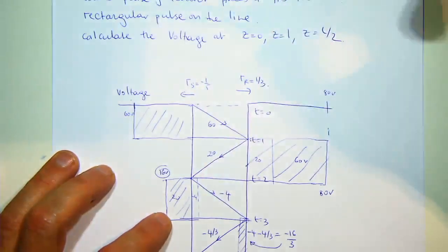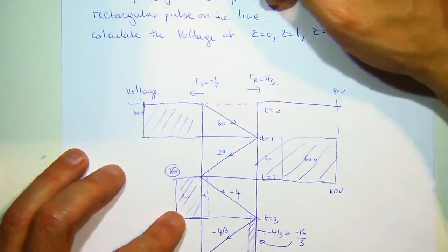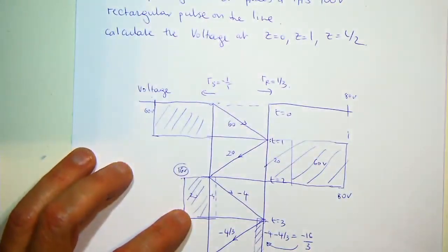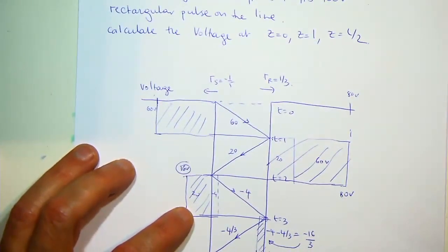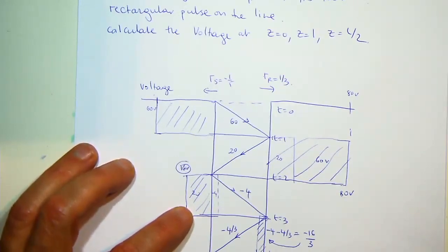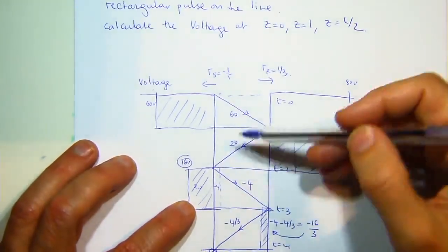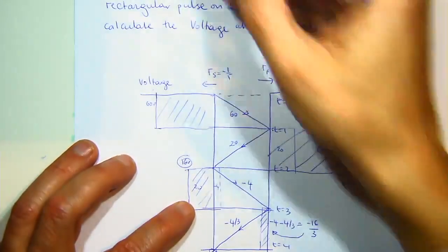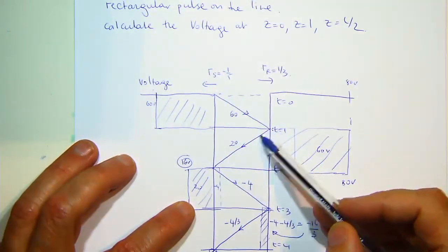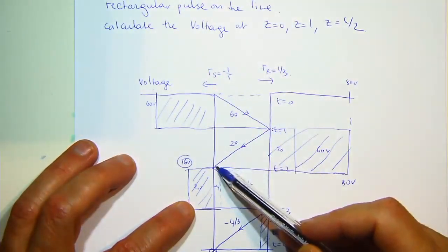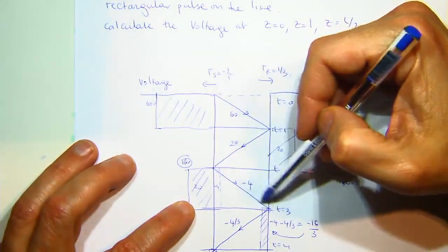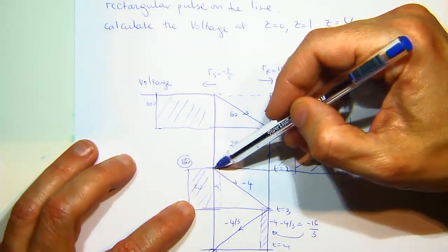Okay, that's my bad. What I assumed when I was describing it was that the voltage generator still had a voltage on it. That's not true. It takes at least 1 microsecond to get back, so as a consequence there's nothing there. The voltage generator has actually switched off. So the only thing that this interface sees is the 20 volts being reflected back, plus the minus 4 volts,